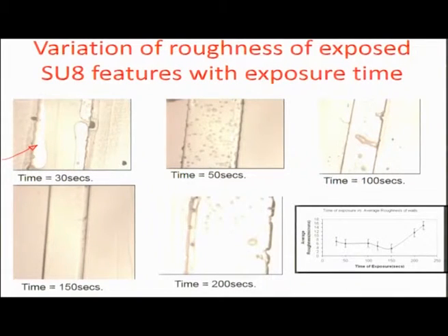For example, this shows schematics, or this shows microscopic images for structures developed. These are like microchannel structures developed for different time instances of exposure. So, in one case we have underexposed, actually both of these cases we have underexposed the surface, and so you can see that probably the proton diffusion is not proper, relating to a lot of wavy edges, under dimensions, because you are not allowing enough time for the exposure and the protonation to happen.